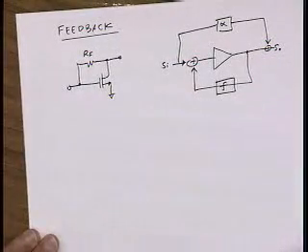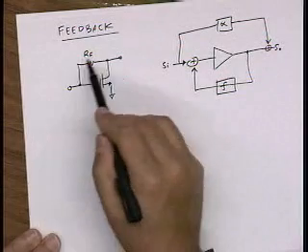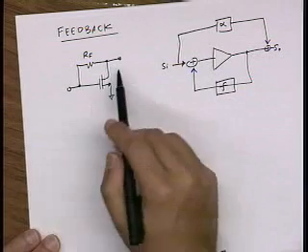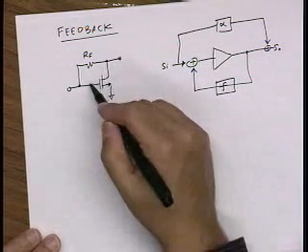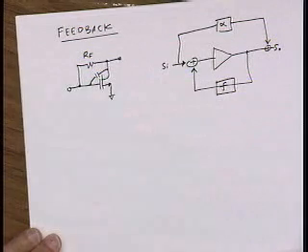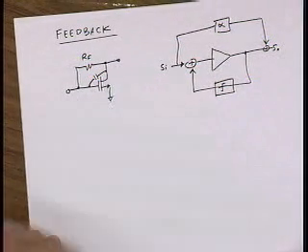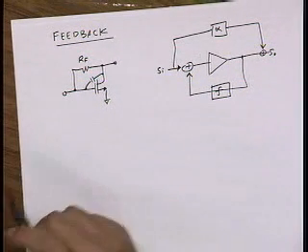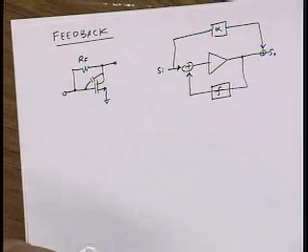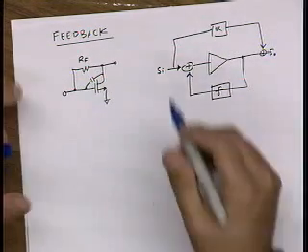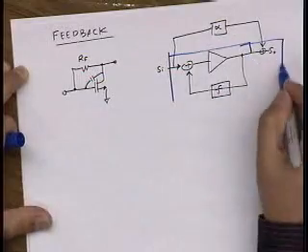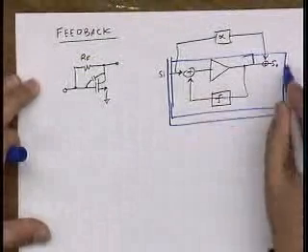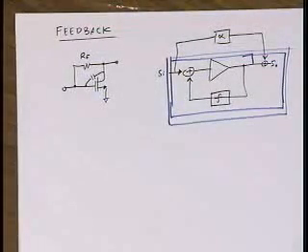and show that some of the input signal can actually feed into the output. Now that happens because, right, a resistor doesn't care which direction current's going through it, so it will feed current back forward, let's say, into the output. Also at high frequencies, C mu will start to feed considerable amount of current in the forward direction. And so we have to watch out for that. That's because our ideal world that we're going to keep analyzing is this world without this feed forward. And if there is feed forward present, you can expect that it's going to mess things up for us, right? Unless we explicitly take that feed forward into account.